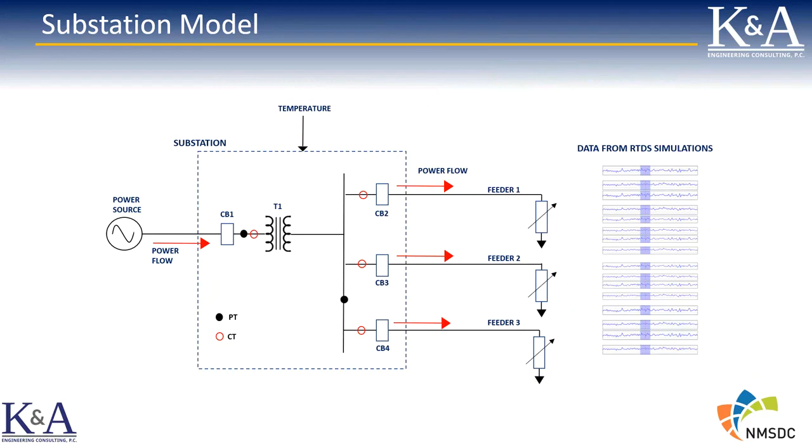And so this is the model that we ran through the simulation. Again, it's the model of the substation. Here we're showing the PT and CT measurement points. We're measuring voltages at the high side of the transformer and also on the station bus, and then we're measuring incoming current and outgoing currents on each feeder. These measurements are PMU data samples at 180 samples per second. Again, phasor measurement units. Again, we collect all of this information. Next, please.